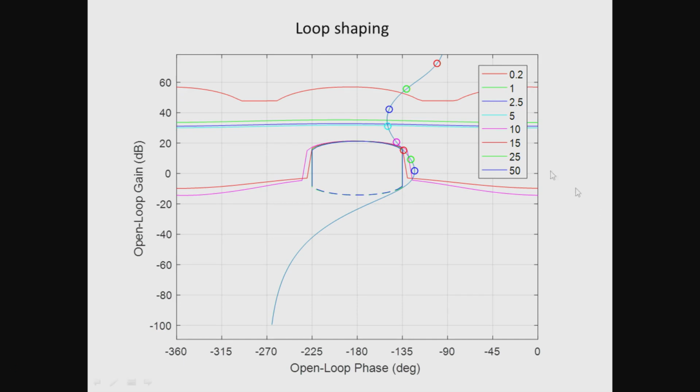You see that the red circle is well above the red bound. So, actually at 0.2 radian per second we have ended up designing a control system that is significantly more conservative than what we would like it to be, but it meets the performance specifications better than what we had intended it to do. And likewise, the green circle represents the loop gain at 1 radian per second, and that is well above the green bound here. The blue circle is above the blue bound, the cyan circle is just on the cyan bound. So, at 5 radians per second the performance specifications are just exactly met.